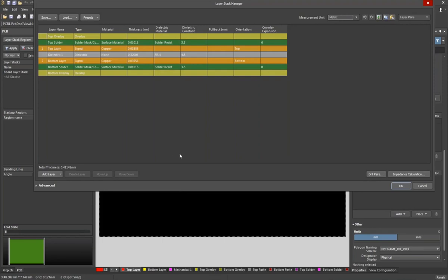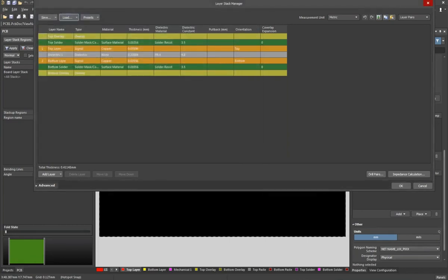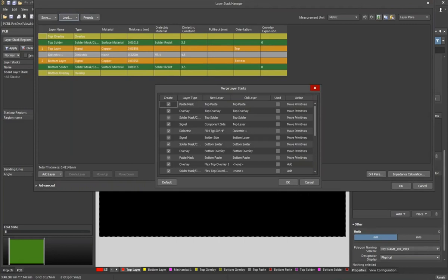Today, we want to show you how to proceed in Altium. So we go to the Altium section. And here you will find the stack-ups being provided. And as an example, I will just choose one. For example, let's go to 1 rigid, 2F1 rigid with a thickness of 1.55 millimeter. So when you click onto it, you are prompted with a new window to download it. So you can download it and choose the right folder. In my case, I will use the webinar folder. So I downloaded it now.